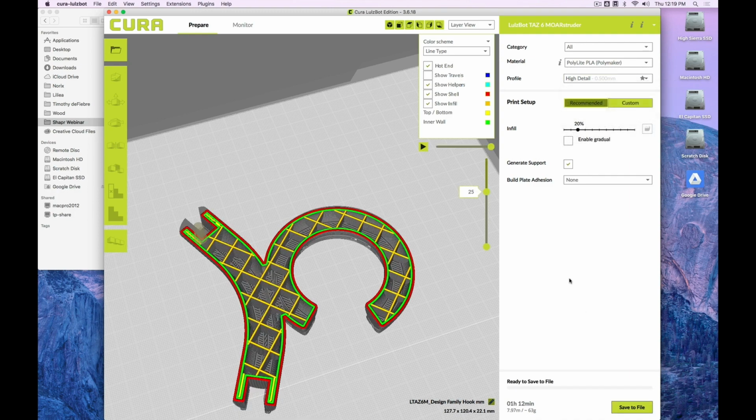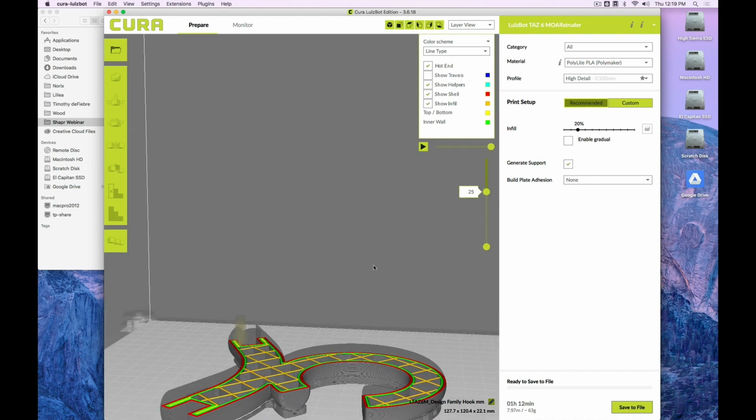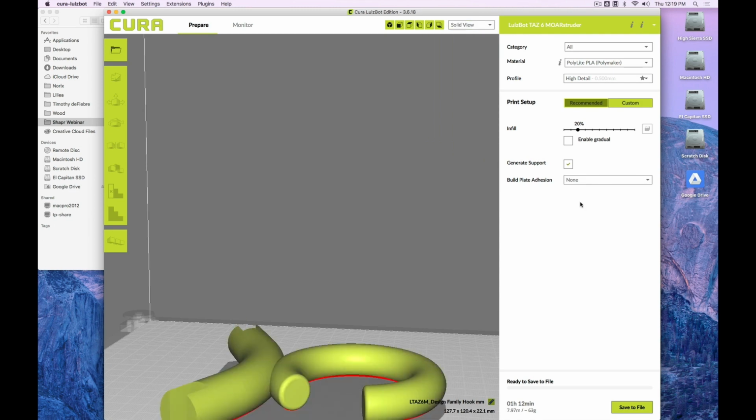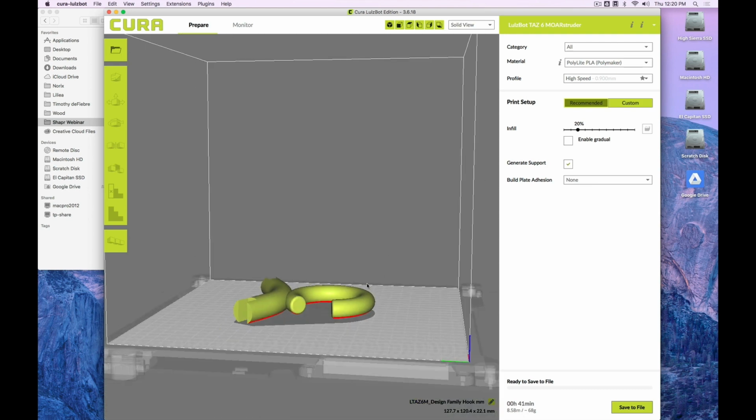So with this actually you can create various layer thicknesses. The higher the layer, the faster you can print. So this is 1 hour, and with high speed, so 9mm material thickness, it's slicing. See, we saved 20 minutes. That's quite a lot actually.